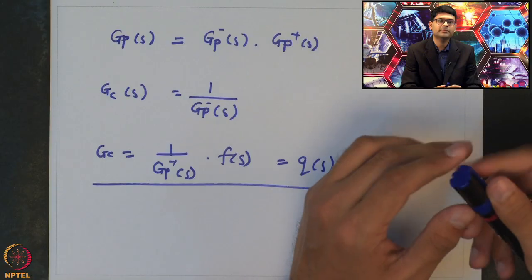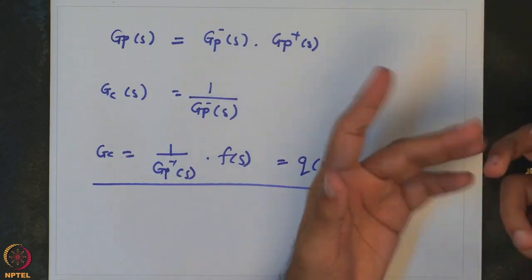Now, we have seen there are some limitations, and mostly they come from the fact that there is no feedback in this open loop control. That also has a significant manifestation in terms of disturbances. If an unknown disturbance affects the system, there is no way this open loop control will be able to handle that. So, in order to get rid of these limitations, the practical implementation of this is known as an internal model control, or IMC.